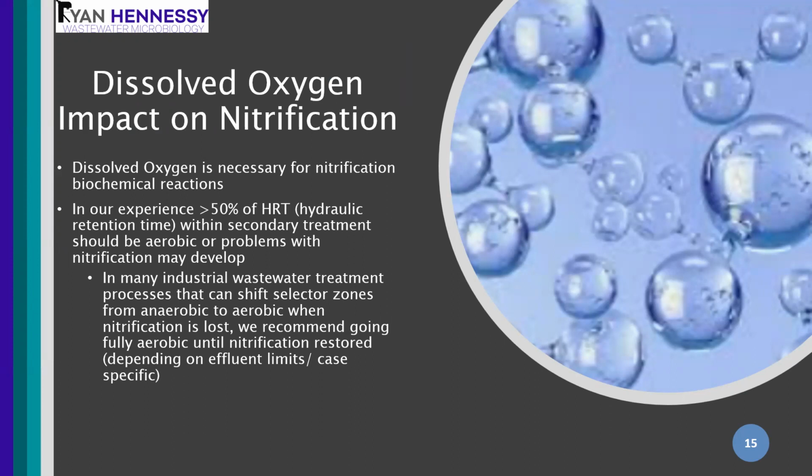Dissolved oxygen impact on nitrification. Nitrifiers are aerobes. They're strict aerobes. They need free dissolved oxygen in order to work. So in our experience, generally at least 50% of the total time that bugs are in the system, they should be aerated.